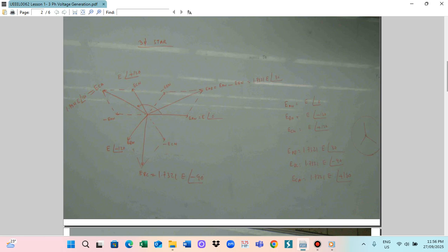Okay, similarly, we can draw the circuit. This is V1, and we represent it this way. This is A, then B, with impedance Z1. This is Z2, this is C, and then Z3, and finally we go to the D point. So ABCD are like this, and we can measure the voltage drop across AD. VAD is equal to VAB plus VBC plus VCD.